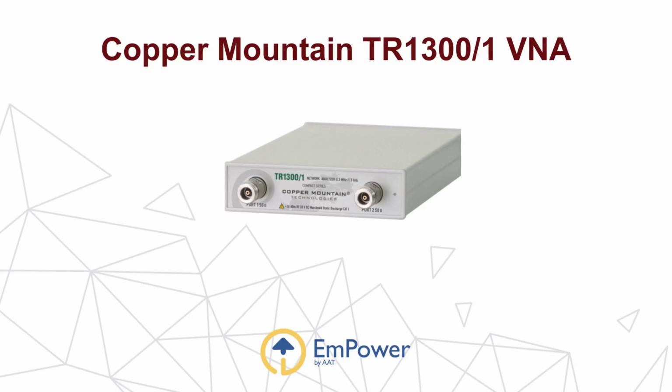So an example of test equipment is a vector network analyzer. We use the Copper Mountain system. That test equipment can be terminated directly to the transmission system, and we can analyze the performance and the characteristic of that transmission system from the point of the termination all the way into the antenna system. It allows us to know where the anomaly is, know where the fault is, or know if any changes are occurring.